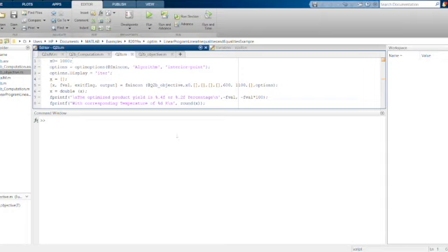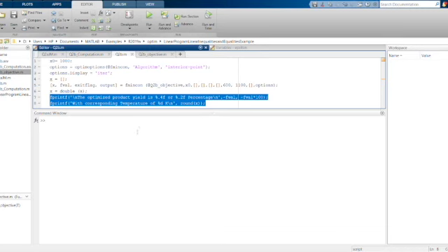Inside the Q2B file, we solve the optimization problem. Firstly, we set the initial point at 1000 Kelvin, as we know from the graph generated before that the maximum point was around 1000 Kelvin, and therefore we set it as our initial point. After that, we set up the maximization problem and call the fmincon function to compute the nonlinear objective function. Then Q2B objective is called, together with the initial point, the lower bound 600 and the upper bound 1100. Then the result will be shown over here.